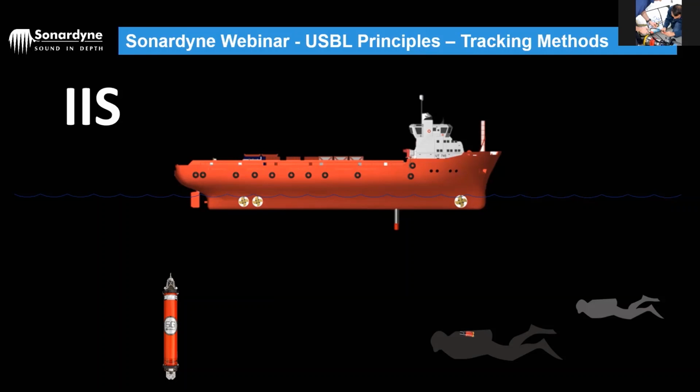So the individual interrogation is specific to one beacon. That means that's the only one that will respond, and it will respond with what we call a common response signal. So it's basically saying, 2101, where are you? Common response would be, here I am, because it's the only one that's going to respond, so it doesn't need to tell you its address. So that's basically what goes on. Individual interrogation, common response, individual interrogation, common response. So that's tracking things individually, or single interrogate.